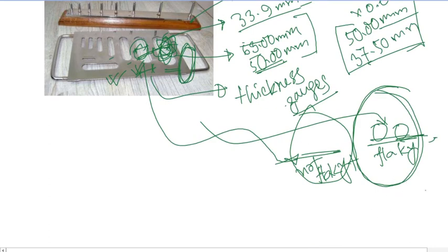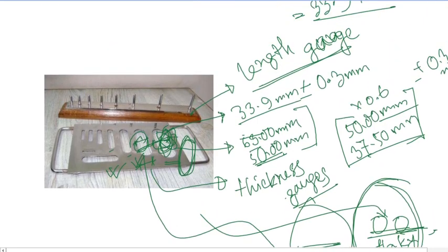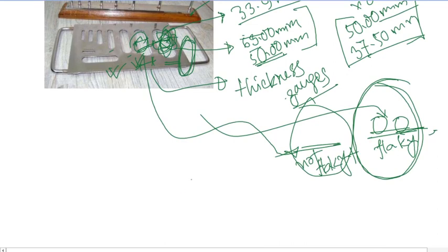But before that, the calculation also being the same, I will be discussing something about the elongation index as well. So what is the condition for which we will denote any particle as an elongated particle or not? The condition is again the greatest dimension.